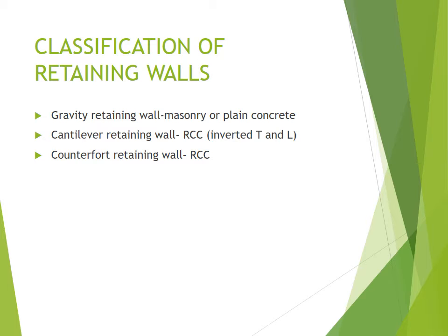They are sometimes referred to as mass retaining walls since they rely on their weight together with friction on the side of the base to overcome the tendency to slide or overturn. They are limited to an approximate height of 3 meters if inclined or 2 meters if the wall is vertical.